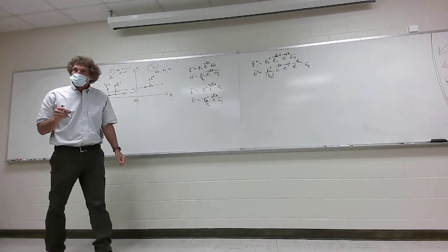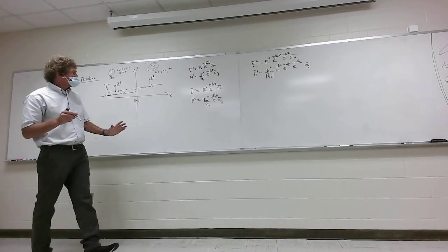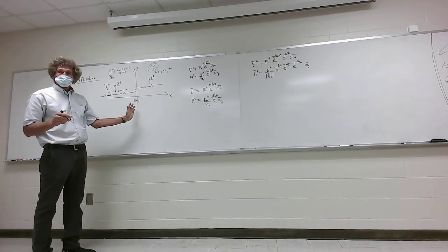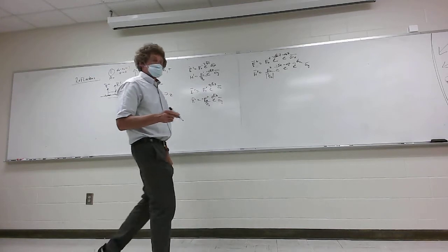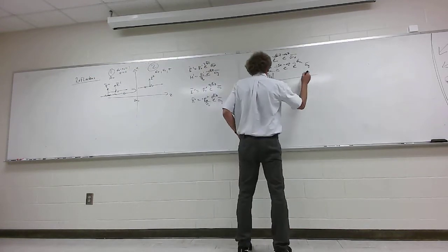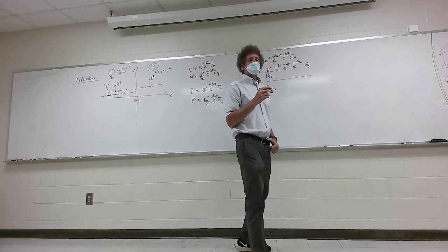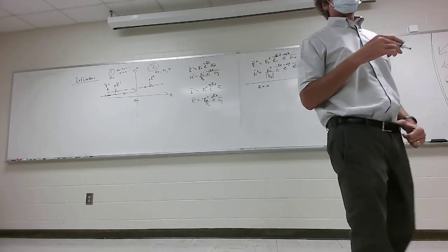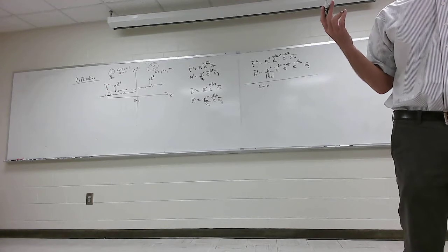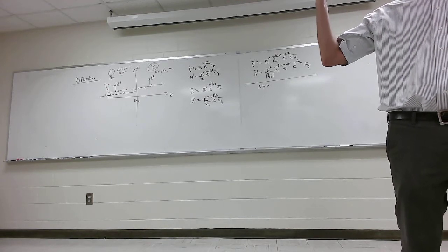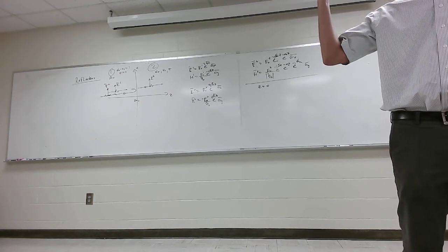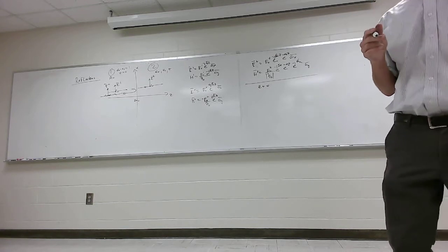All good. All right, now what we're going to do is we're going to look at what happens right at this boundary. So now we explore, and this is the key thing. Now we look at z equals 0. So at z equals 0, it gets rid of all those e to the j beta things, right? Because z is 0, e to the j 0 is just 1, isn't it, class? So that's the reason we put the boundary at z equals 0.